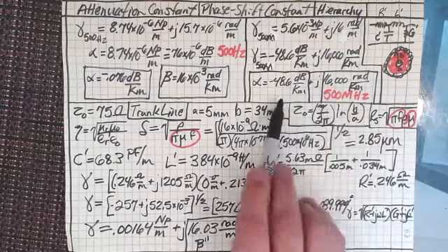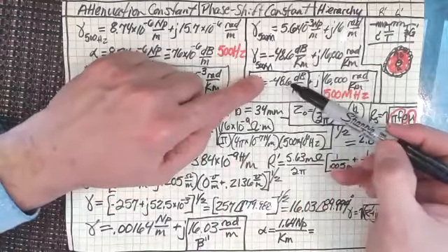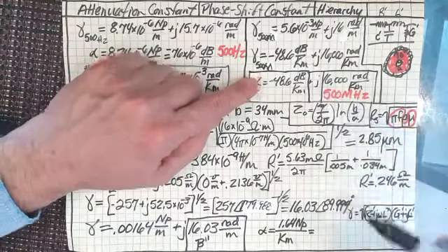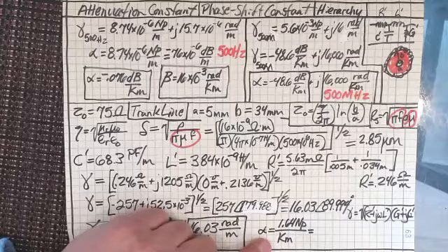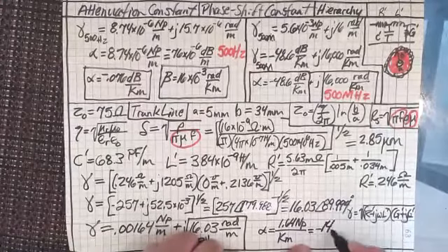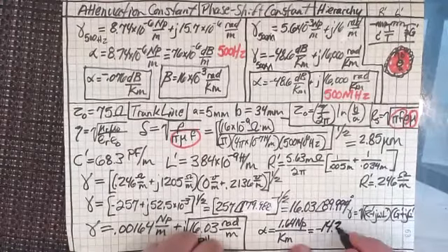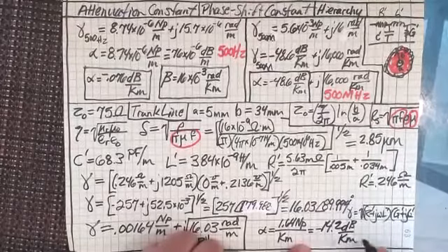Let's compare the kilometer attenuation. Now, this is the cable behind your house, right? Or behind your TV set. This one gets minus 48.6 decibels per kilometer. Well, if I go out to the trunk line, though, that's in front of your house on the telephone pole, I end up getting minus 14.2 decibels per kilometer.